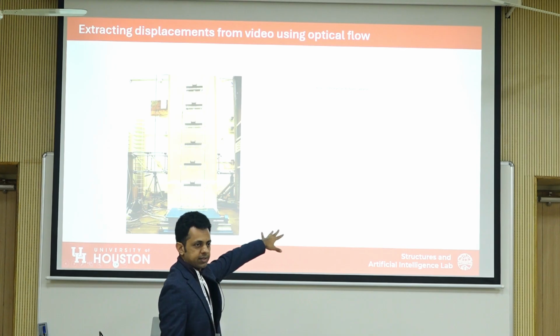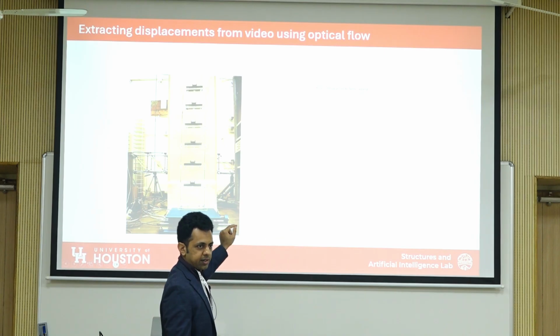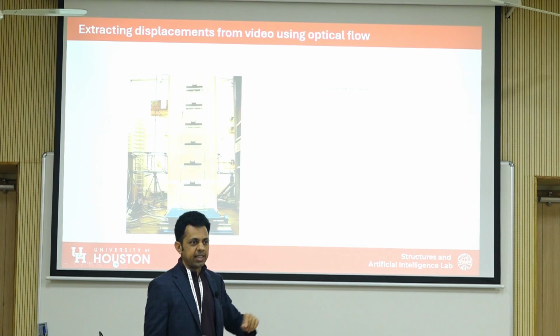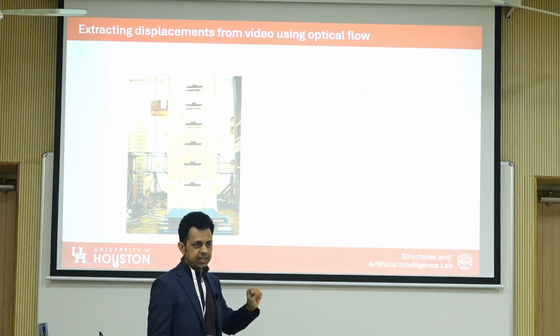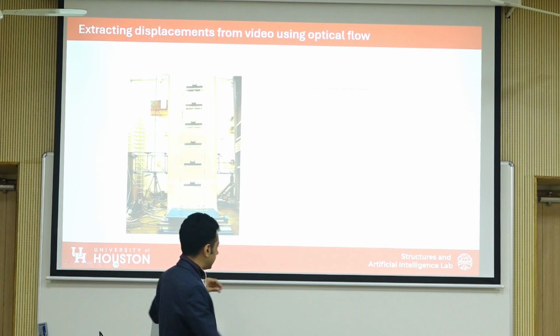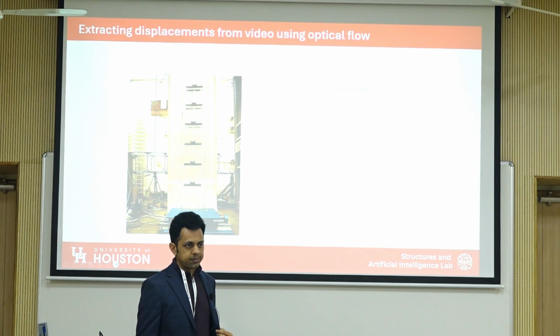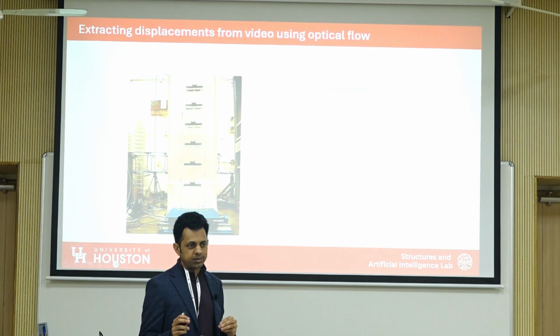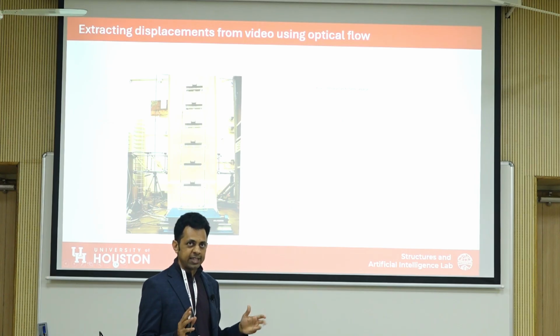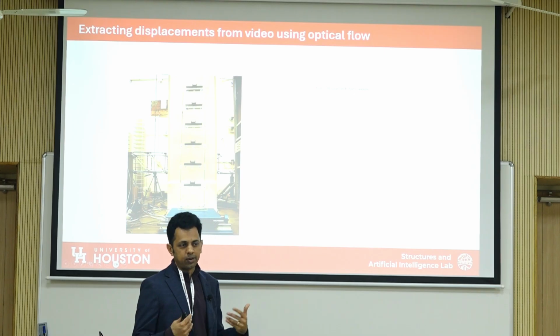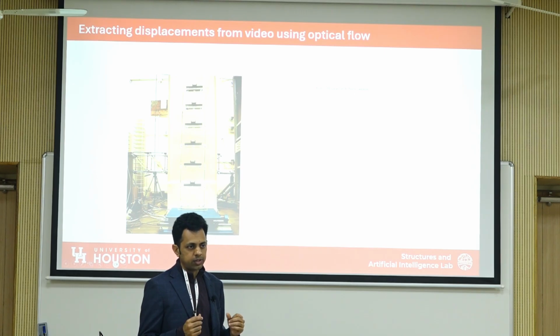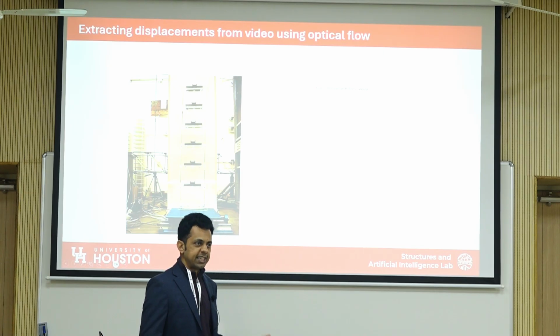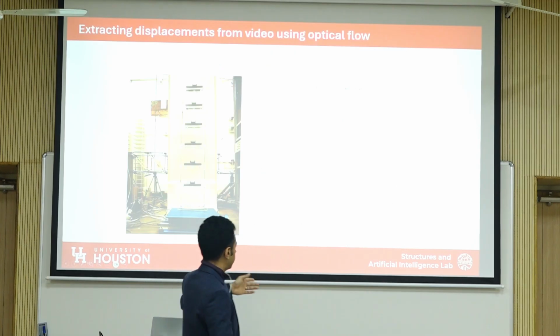So I have 6 displacements, one at each story, so it's like a signal. And then I'm using the eigensystem realization algorithm, the NExT-ERA method, because here I have a broadband white noise excitation. So I'm using the NExT-ERA method to compute the mode shapes. I talk about that because it's not a vision-specific method; it can be applied to acceleration. It can be applied to velocity also. But essentially, you're getting this displacement signal here.